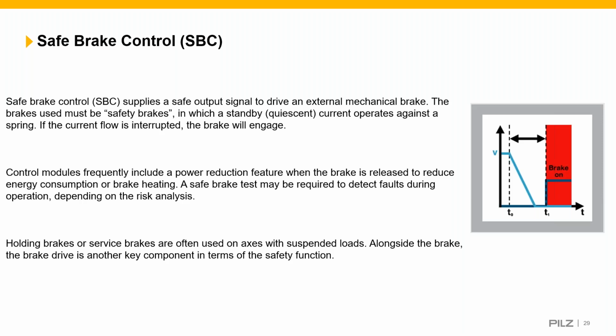If the current flow is interrupted, the brake will engage. So it's fail-safe. Control modules frequently include a power reduction feature when the brake is released to reduce energy consumption or brake heating. A safe brake test may be required to detect faults during operation, depending on the risk analysis. We'll cover that, the safe brake test, shortly as well.